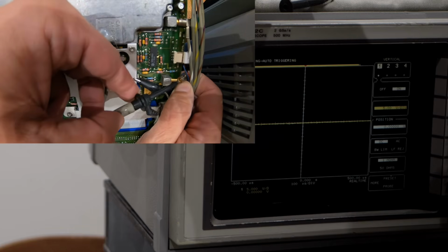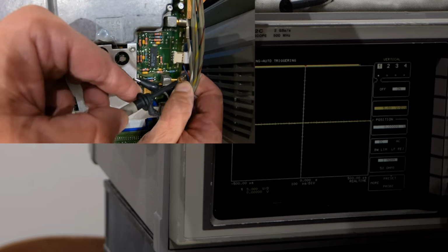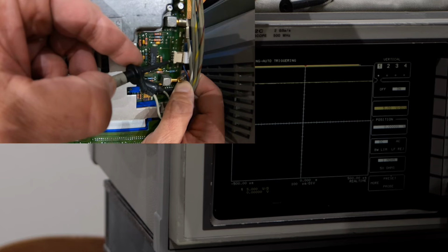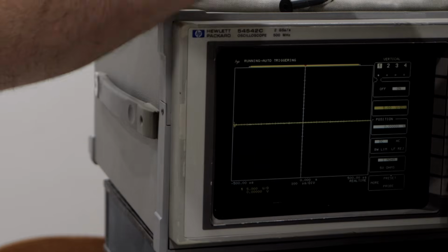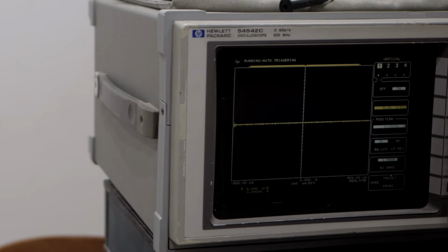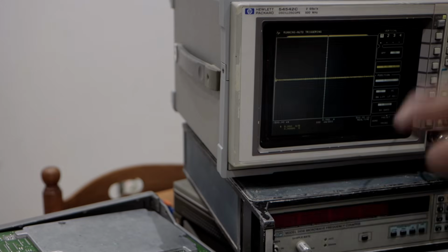Now measuring the oscillator output, no signal. Double checking the supply voltage and control signal again. Yeah, still okay. So at least the issue of the A21 oscillator is definitely not on the power side.